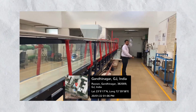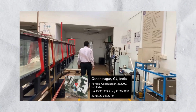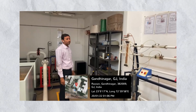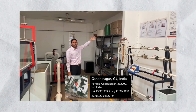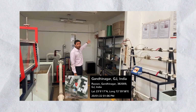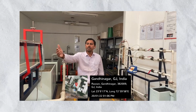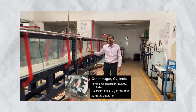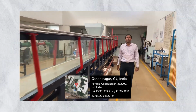In addition, we have these facilities for hydrology and water resources engineering. As I said, the rain gauge, this green equipment, is a tipping type of rain gauge utilized for measurement of rainfall. Beside it we have the infiltrometer, helpful for measurement of infiltration. The next instrument, just beside this hydraulic tilting flume, is the pan evaporimeter, which is utilized for finding the rate of evaporation.